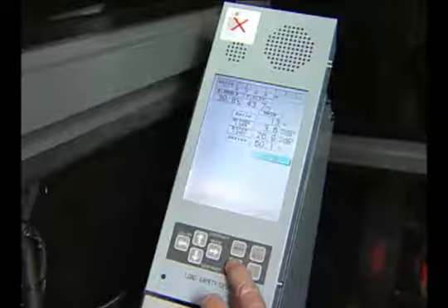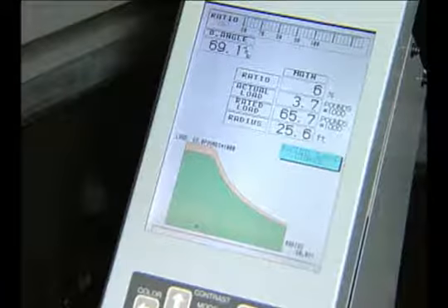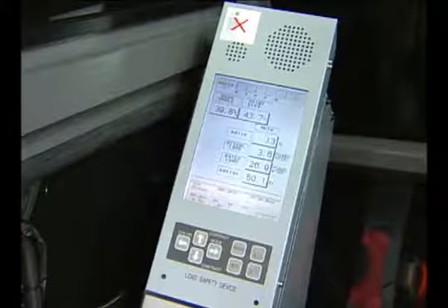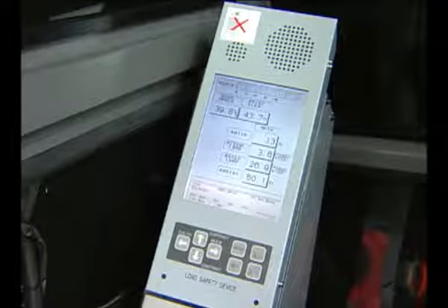The three main parts of the Kobelco LMI include the large color main display, which works together with the main machine's total controller, the hardwired load cell located at the lower spreader, and the angle sensor located inside of the boom base section. We'll now discuss the main monitor display inside the operator's cab. Just above the display screen are two buzzers that give audio signals for the different types of warnings. At the top of the main display screen is a bar graph that starts at 60% ratio and gives the operator a visual of current load status.